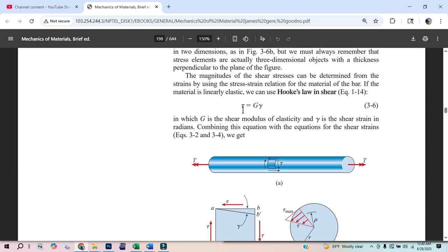Like I said, if I say that 44,000 is the force on the area in shear that steel can take, given 1 square inch of steel shearing it, and the angle that's going to form is 0.004. Cool. If this is 0.004 and this is 44,000, what's this? It's 11 million. So this value is just 11 million, and it has units to match.